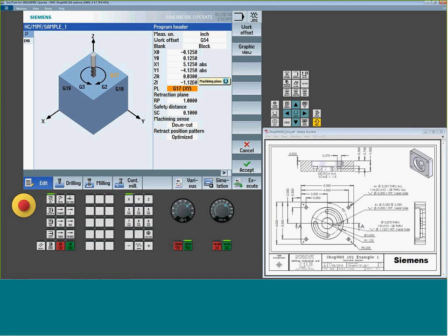Okay. Then you have your default tool plane. This is going to control what the canned cycle knows the z-axis orientations to be. So I can set it to G17, 18, or 19. So let's say you had a right angle head. You could tell it you're in a G18 orientation. And now your drilling cycles would actually drill in that orientation. Or I'm going to stay in my standard G17 plane for a vertical machine.